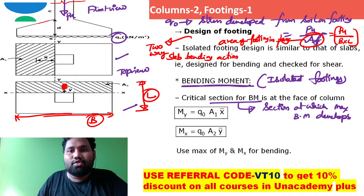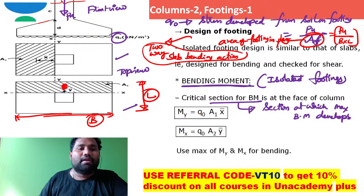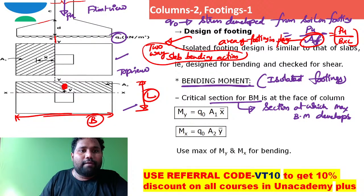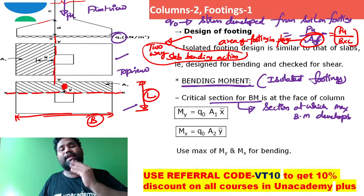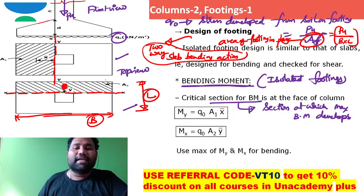As it is having two-way slab bending action, the bending moment will be developed with respect to the y axis separately, and the maximum bending moment is possible with respect to the x axis also separately. Now the question is, sir, what is the maximum bending moment that is developed with respect to this y axis?